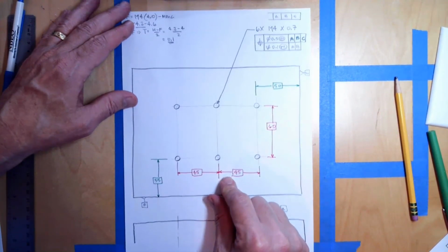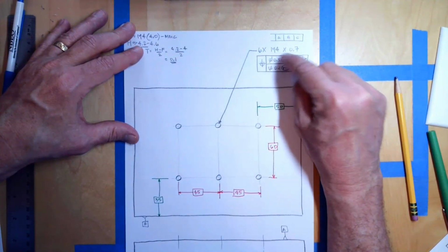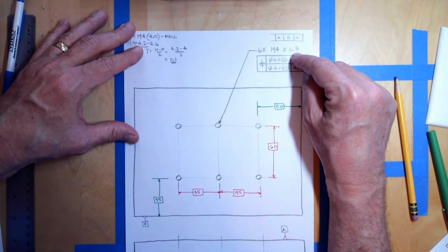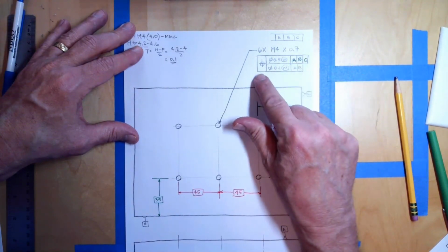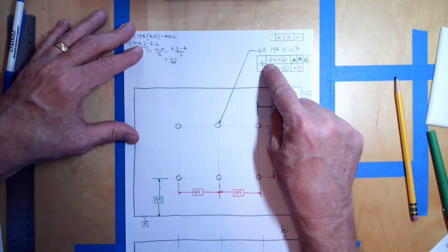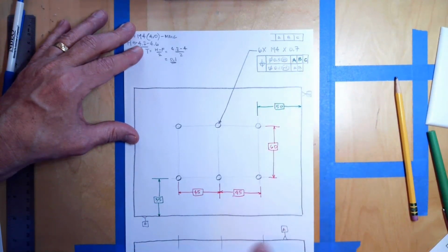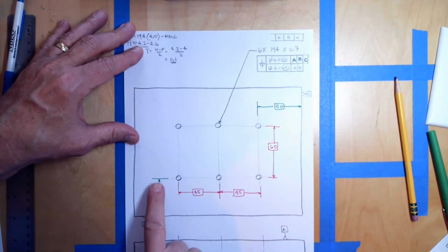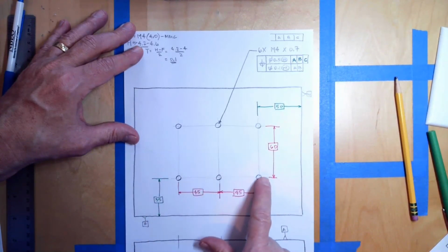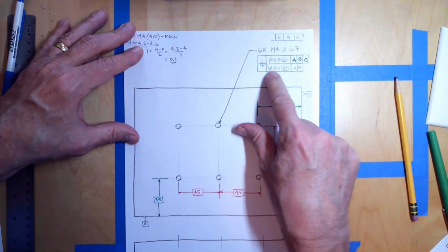But in terms of these 6 holes, we have 6 holes that are M4 tapped with an M4 by 0.7 thread. They're located relative to ABC with a tolerance zone of 0.5 at MMC. And A is understood to be 90 degrees, right? We don't need the dimension for that. B, they're located from B, 35 millimeters basic. And from C, 50 millimeters basic.